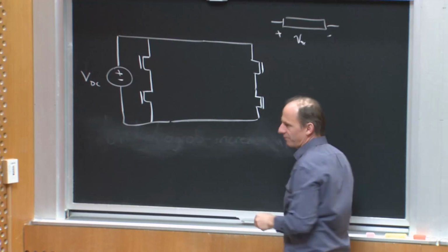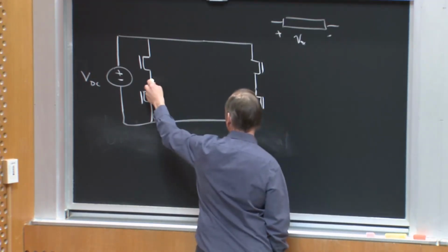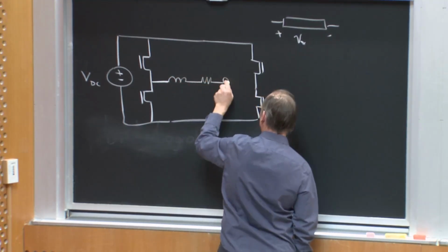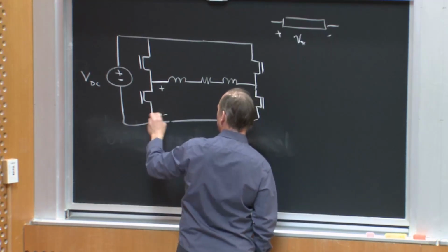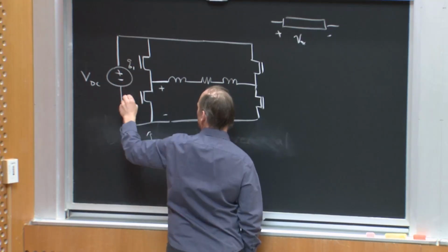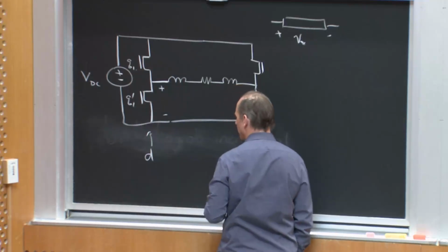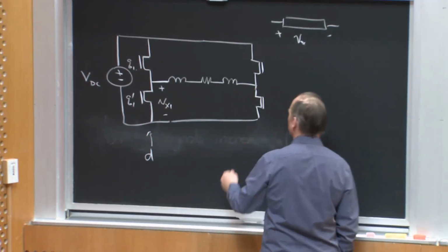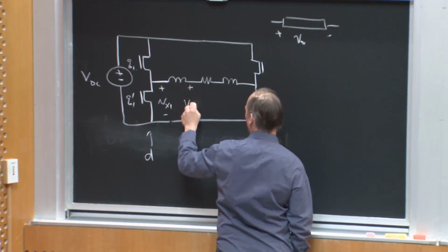element that we're going to have as a filter. But imagine you constructed the structure like this. Suppose I had an inductor, a resistor, another inductor, okay? Then I could consider that I'm synthesizing on this side of the circuit, if I have Q1(t) and its complement, so I have a duty ratio of the top switch on this side of the circuit, I could generate some output Vx1, okay? And that might be filtered through this inductor, might generate me Vo1.